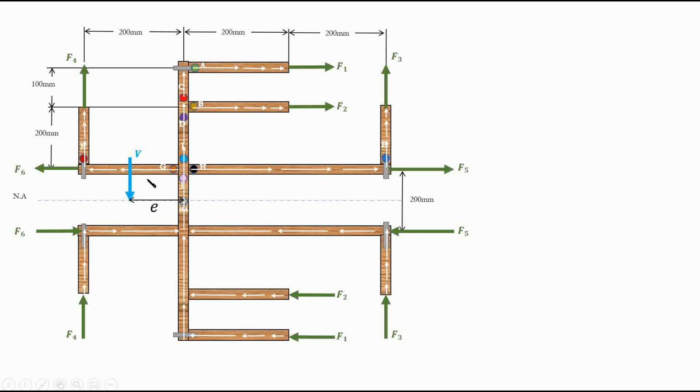In fact, I will end up with an additional twist in my section, right? So based on the assumptions that I made, I will basically have to recalculate everything, because that's against my assumptions. Those are not the assumptions that we have in our shear formula. So what we do is find the shear center to avoid additional twisting.